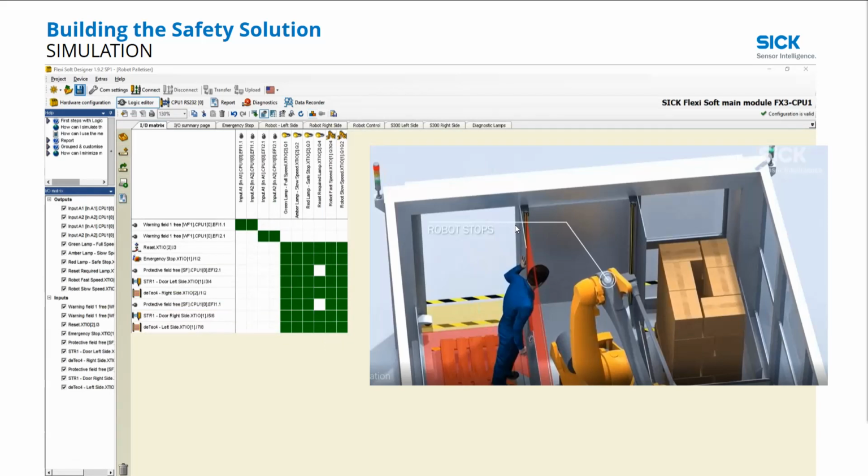What you have to do is work out how to write the logic before you actually write it. So you need to have almost like a truth table like this of how you want the relationship to work. So that's simulated the logic, and we're now quite perfectly happy with that. Now, as well as simulating it in working conditions, you'll also simulate it in fault conditions as well. So you would have quite an extensive validation and verification test schedule for something like this application.